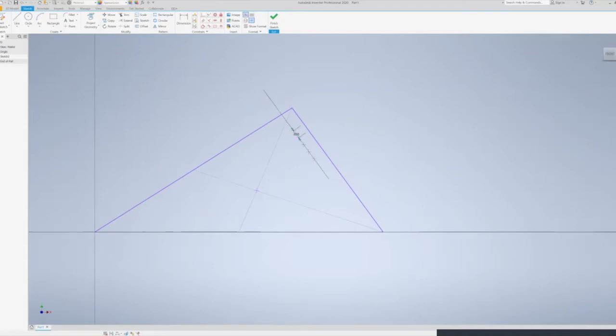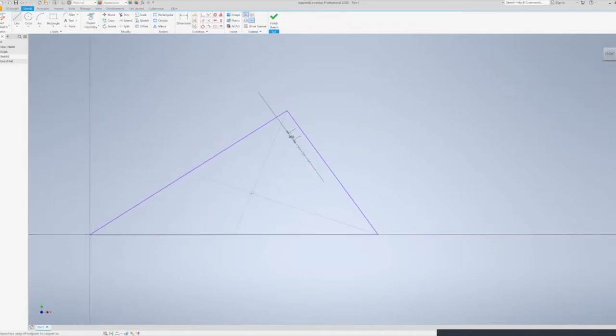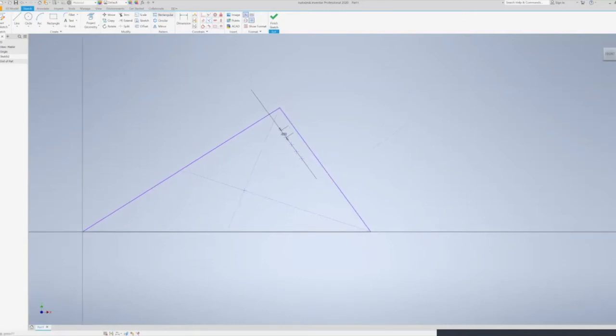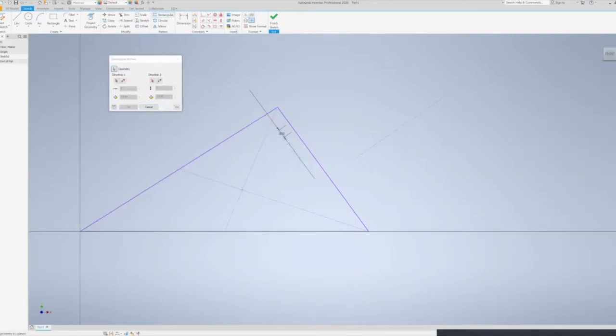And if we wanted, we can make rows and columns of points just by applying the rectangular pattern again along a direction perpendicular to this side right here, if we wanted it to be a true rectangle. So let's do that. We just put down a line, and we could use the perpendicular constraint to just make it perpendicular to this side right here. And if we select the rectangular pattern again, we just drag over all these points to select them all. We could press this button and select this line. And that will guide the direction of the duplication this way.